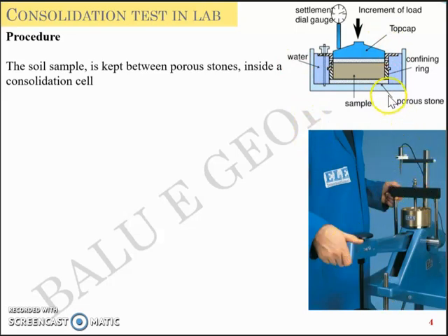So basically your intention is to squeeze the soil and to see the rate at which there's a reduction in volume. So consolidation basically is a reduction in volume. It is due to expulsion of water, and it's due to a static load. So we have a mechanism by which you apply a static load here, and the load frame comes over what we call a consolidation cell, and the load frame is attached to a lever arm in which you can have the option to have dead weights.